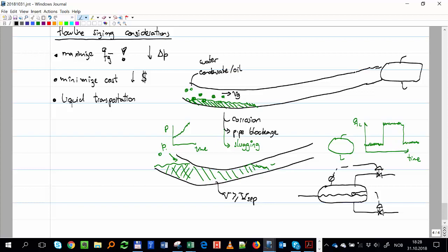So what do you think will happen if I receive that whole block of liquid at once? No matter if I put fully open valves here, it won't manage to keep the pressure constant. You will have liquid coming into the gas line, liquid coming everywhere in the system. And then when I have a batch of gas, it has the same effect: the liquid goes very low and you have gas in the liquid line, a catastrophe, a disaster. So in those cases, I don't want to have slugging. I want the gas velocity to be enough to take the liquid out continuously and avoid accumulation of liquid.